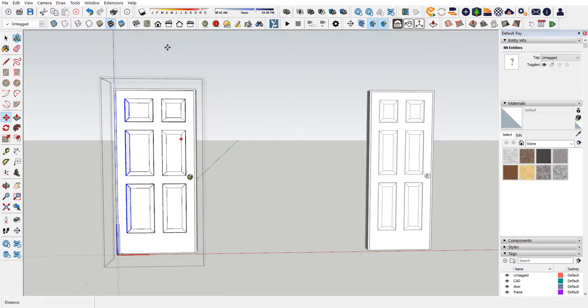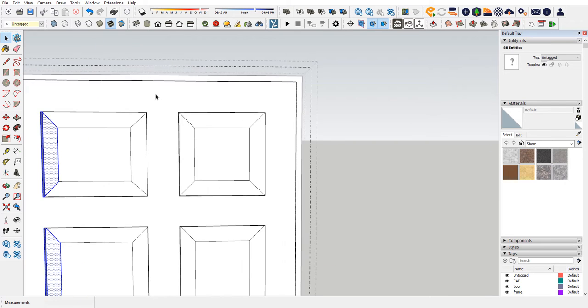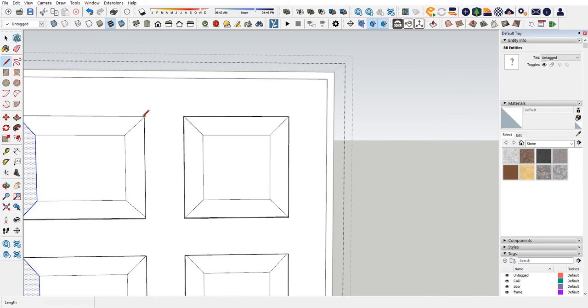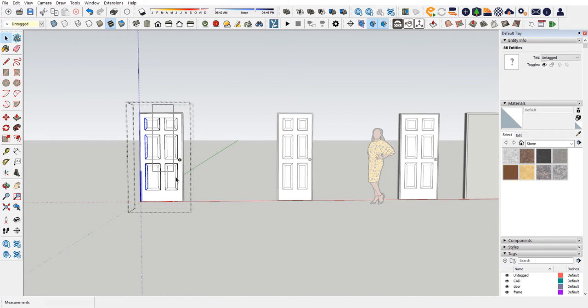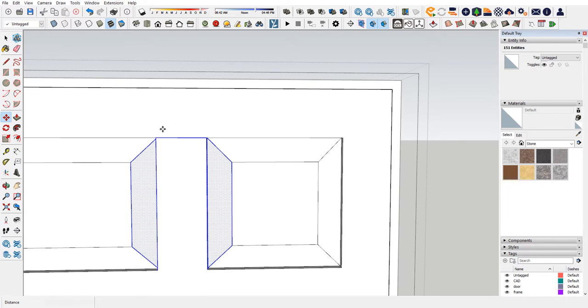And again, we got the other option, the other problem before. This one came too narrow. This one got wider than this one. Same solution. L for line, click, click, and then I'm going to select. Remember, select first, then do. We're going to select the same middle pieces plus that line that I drew. M for move.